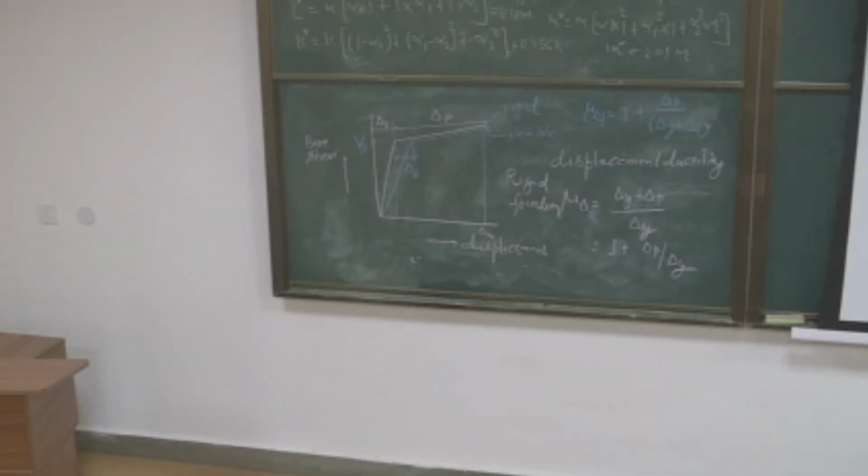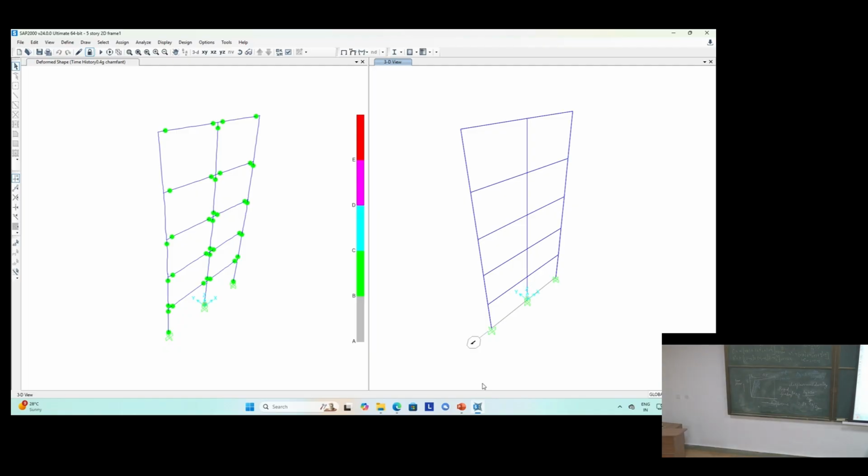In which you have a slab depth of 150 mm. The imposed load is given as 5 kilonewton, that is your highest load in any structure which you do, the live load. And the column size is defined, 450 by 450. Concrete grade and steel grade, the material grades are given to you. Base size is given, and it is a 5-story building.